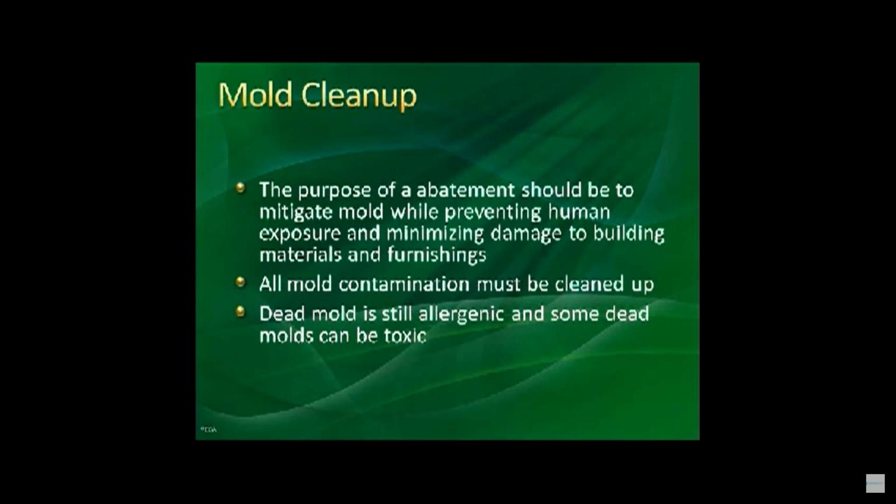The main purpose of remediation is to clean up the mold. It's got to be clean and returned to the nature that it should have been originally, which was clean and mold-free. All the mold contamination must be taken out. You need to understand, dead mold is just as bad as live. And I'm going to discuss this in a couple of slides, from what the IICRC S520, Guide to Mold Remediation and Abatement, is.